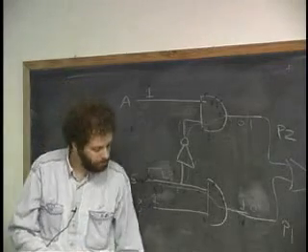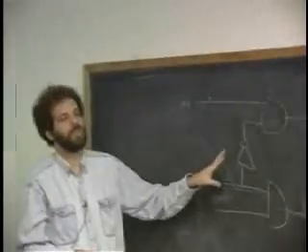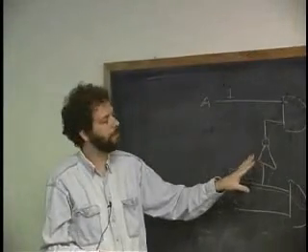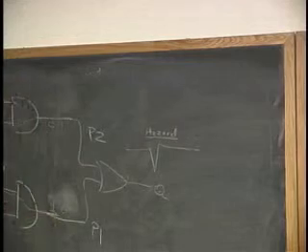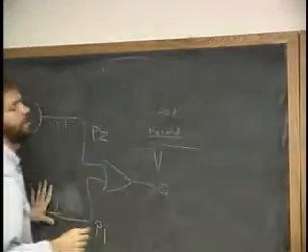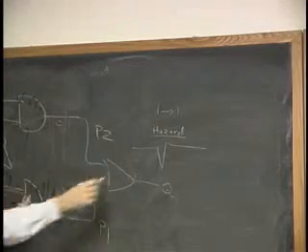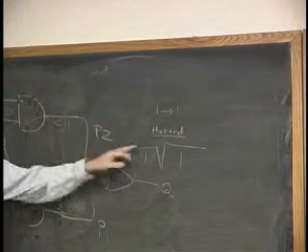And in general, computers inside are filled with problems like this. The technical term for this is actually called a hazard, okay? Like a road hazard. And in particular, this kind of hazard is called a 1-1 hazard, meaning that we started out with an output at 1, and we ended up with an output of 1, and we generated a hazard.